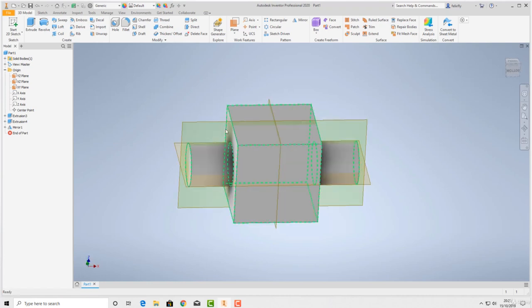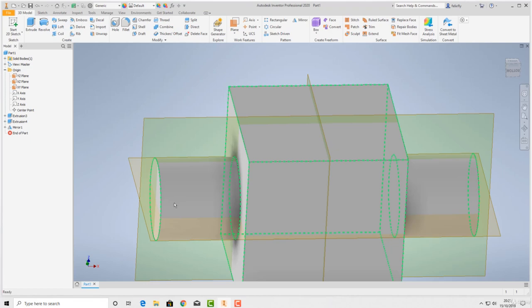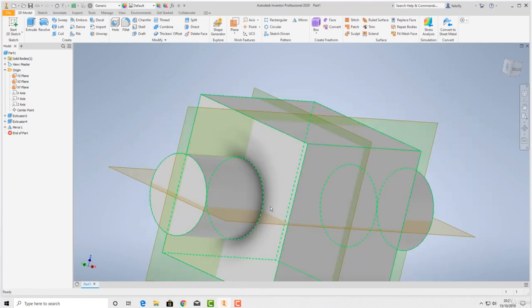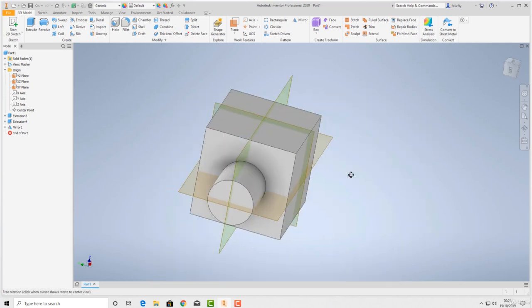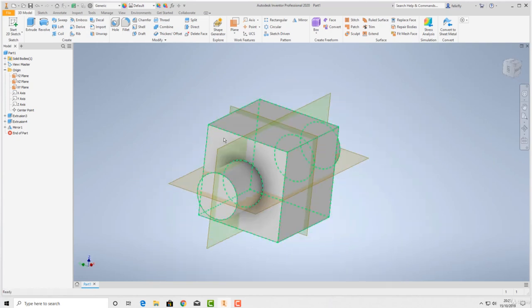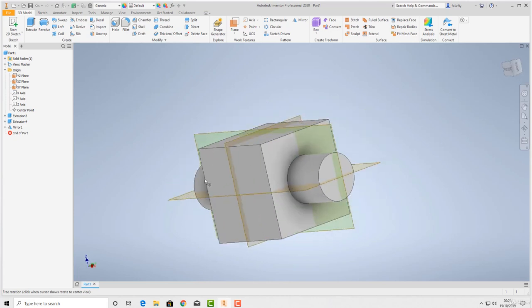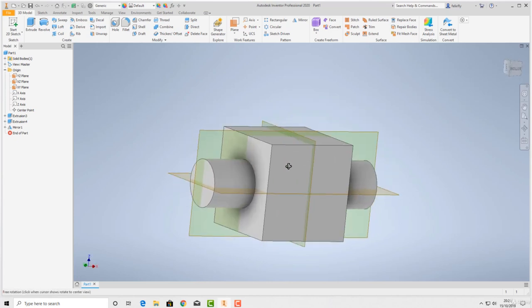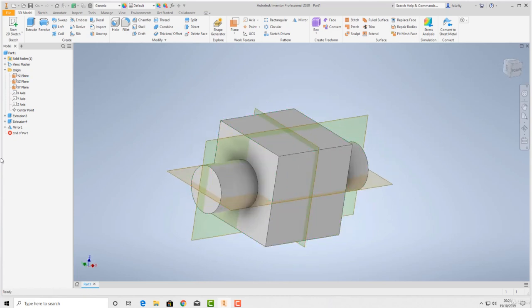This is just a circular protrusion, but if we had some complex pattern or geometry going on this side of the cube and on the other side, it's so much easier to do things once. We could have done all that complicated geometry on this one side and then just said mirror the lot, and it would have done it. Okay. The benefit of working that way is maybe these actually need to be 10mm diameter, not 25.